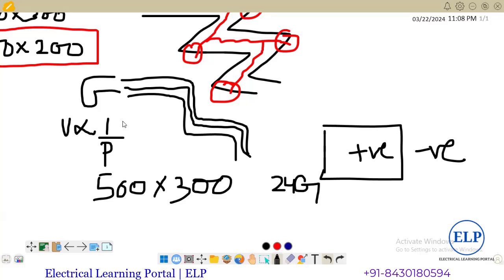See, your circular or elliptical ducts are not designed for the bigger area. Suppose rectangular duct you have to provide, it is for the long term. And insulation is always best because you are supplying the cool air.